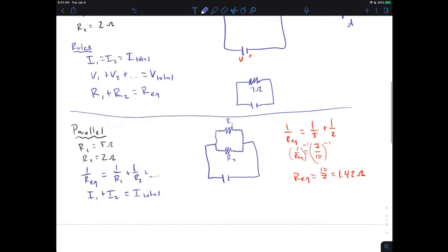And the other consequence here is that here I start, let's say, at 10 volts. When I go across this first resistor, this is the only thing in my way. So 10 volts, resistor, home, right? So at home, I'm 0 volts. When I start, I'm 10 volts. So when I go across this resistor, I have to drop those entire 10 volts. All my voltage is dropped over that, right? So I have 10 volts here. Or if I go the other way, I still have to drop those 10 volts, right? Remember, I have to spend all my voltage by the time I get back, so I can spend it all here. So in both of these